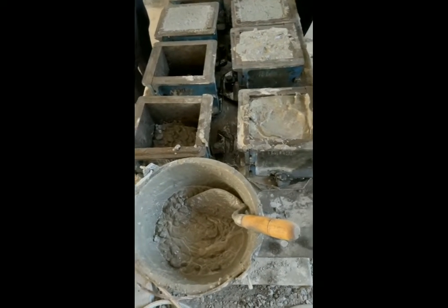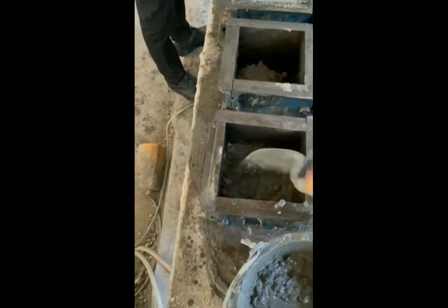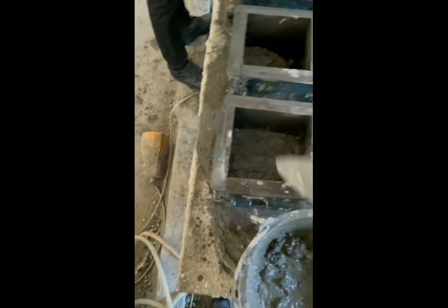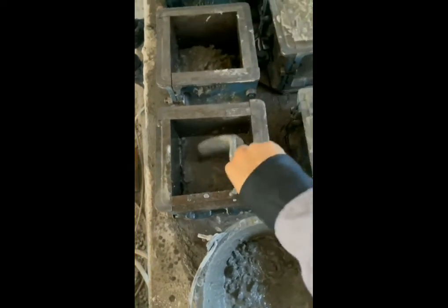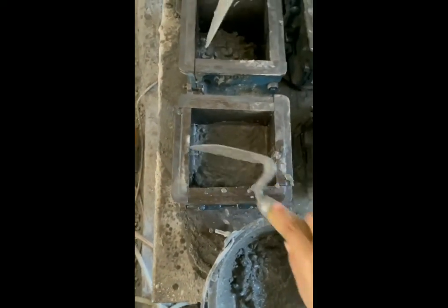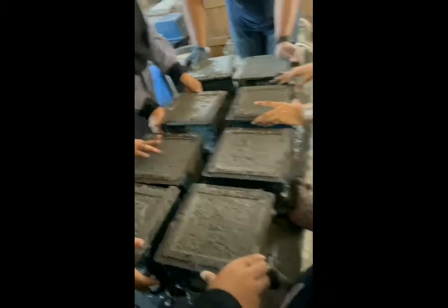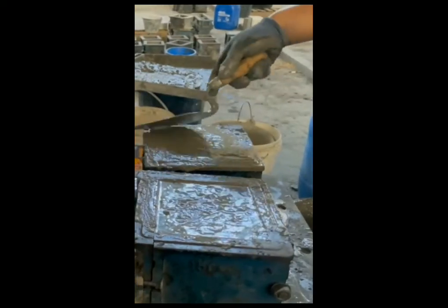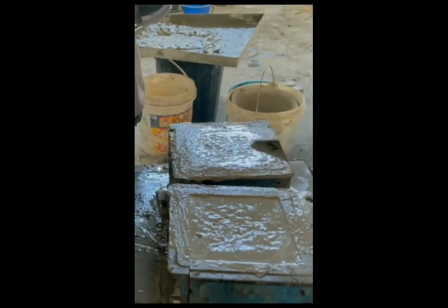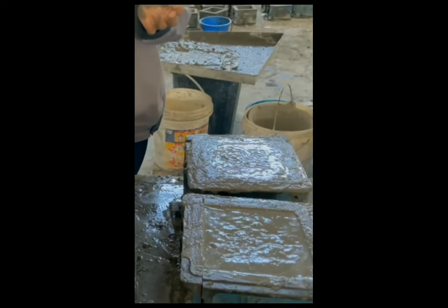Casting cube concrete. The cube mold was cleaned and a thin layer of oil was spread on the surface of the inner side. The cube was filled approximately 1/3 for each of 3 layers. Each layer was compacted using a vibrating table until the specified condition was attained. The surface of the concrete was finished level with the top of the mold by means of the trowel after the top layer had been compacted.